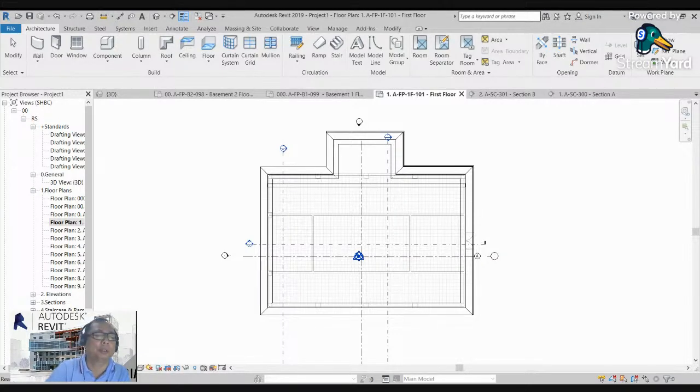Para dito po ba sa Revit, we can see po the future discrepancy in architecture and structural? We call that clashes, not discrepancy. Clashes. So, makikita agad dyan once na dinedevelop nyo na yung model. Doon pa lang sa pagmo-model, makikita nyo kung saan na yung sabit. And then, merong mga coordinator, pero usually, we are using the Navisworks.